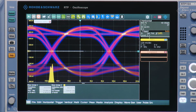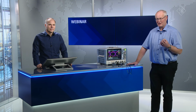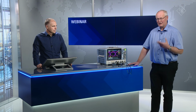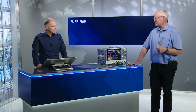single-ended measurement here. If you measure differential high-speed signals, single mode is not sufficient. You have problems with disturbances on power supplies that may introduce common mode contributions. And also you have to trigger with the serial pattern trigger in order to avoid ambiguous jitter results, histograms, depending on the data edge. So you need both the differential mode and the capability to trigger properly on the differential signal. So having said that, I would like to return to Guido.